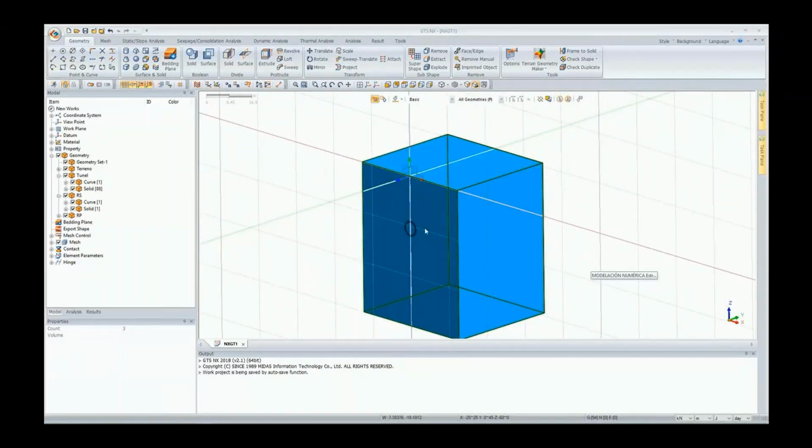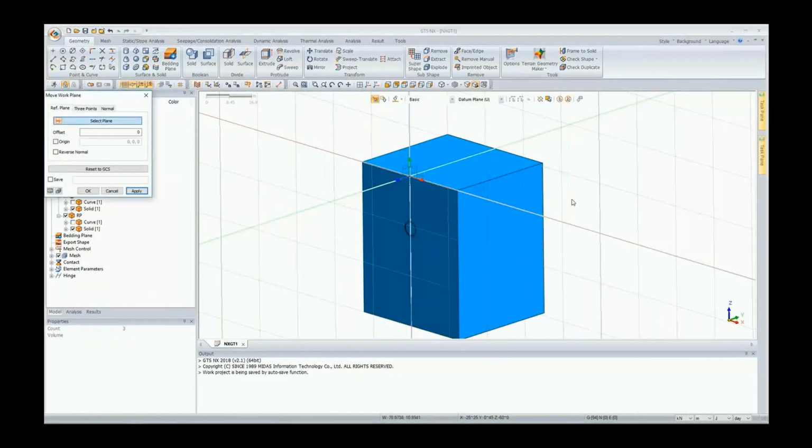and now we need to divide the solid by the strata layers, and we can also see that these solids are still independent of each other. If I hide the tunnels, you can see that the cube itself is not represented as a connected tunnel. So we're going to have to account for that as well. But what I first want to do is generate the surfaces to divide my strata layers.